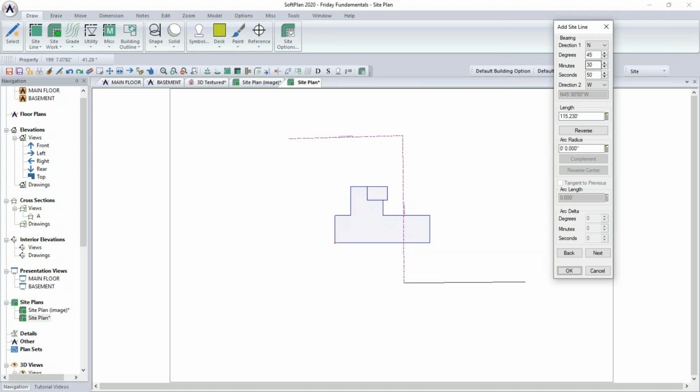It's not the direction it needs to go. It needs to come in the opposite direction, or more specifically, the reverse direction. And that's what the reverse button does. So if you are entering surveyor's coordinates, you'll likely discover that in most cases, they're all in a north bearing. And you can do so and enter them as they are given to you. But as necessary, we can reverse that direction, which is what I've done here.